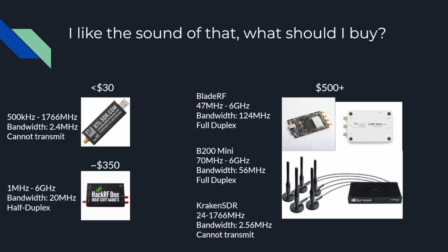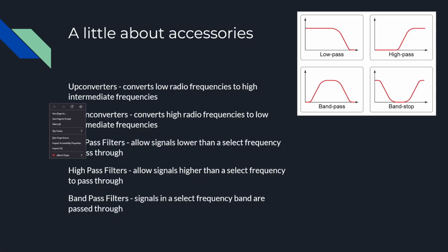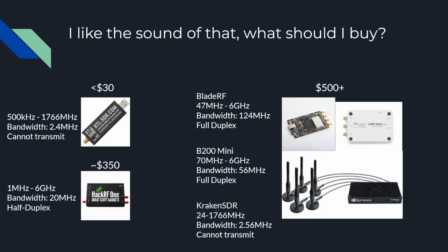The bandwidth here is how much of the radio frequencies these radios are going to be able to catch all at one time as it's listening. So let's say that you're listening to a trunked radio system from 800 megahertz. Let's say it has 4 channels, and it's 800 megahertz to 816 megahertz, and it's split evenly. So it's like 800, 804, 808, 812.